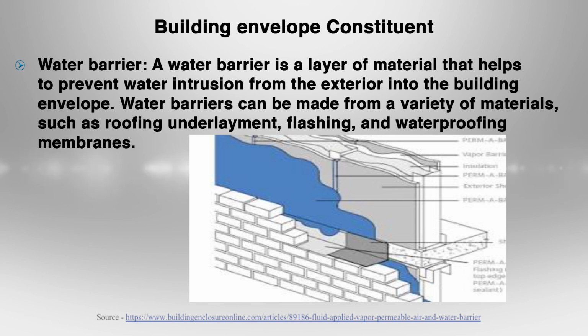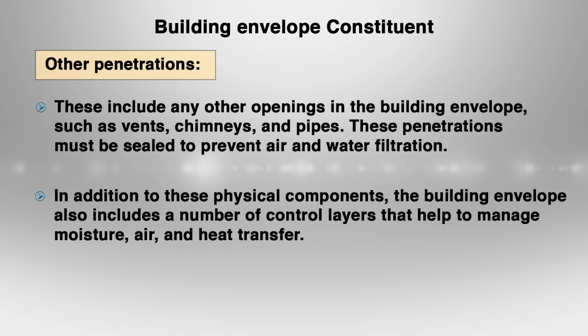These barriers extend the lifespan of building materials and water is a major enemy of buildings. Water intrusion can lead to structural damage, mold growth and unhealthy indoor air quality. Ensuring that air and water barriers are continuous and properly sealed in all joints of the building and penetrations is useful for their effectiveness.